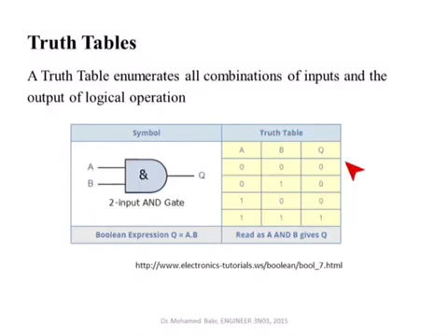So this is called the truth table. And again, I would like you to imagine that A and B can be either logical variables or they can be signals. And these signals can assume logic 1, meaning a high value, 5 volts or 12 volts, whatever the case may be, or they can assume logic 0, which is a low value. It can be 0 volts, can be -5, or the case may be. Okay, so remember this AND gate is extremely important.